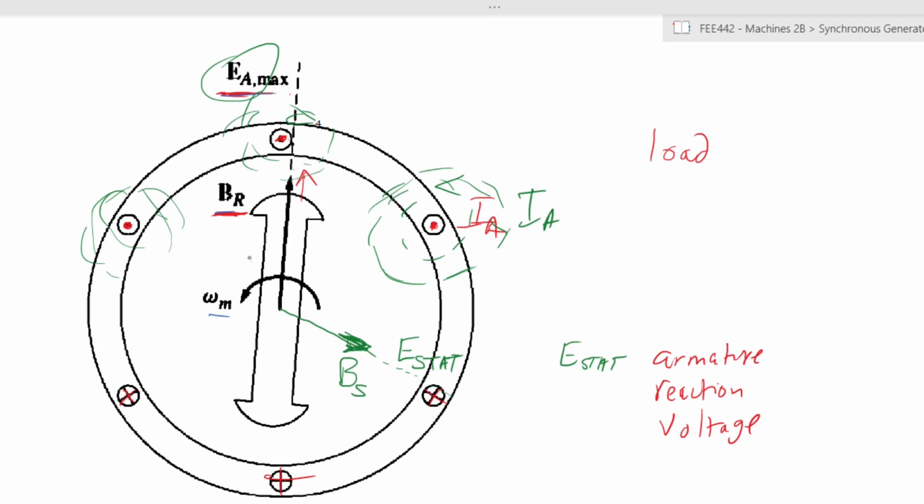So in the end, in this same space, you have your BR and you have your BS together. What then happens is you end up with a net field here, depending on the magnitude of the armature reaction, a net field which is the resultant of this. I've not drawn it to scale. Call it that. If you were to superimpose the net effect, if you add BS to here, the resultant is B net. Sorry, the scale was not very good. Let me try and retroactively amend that.